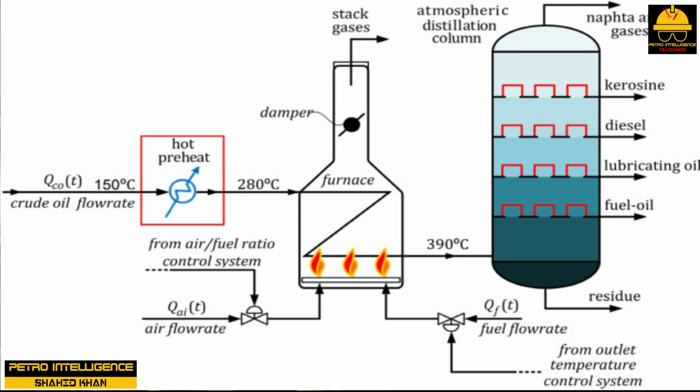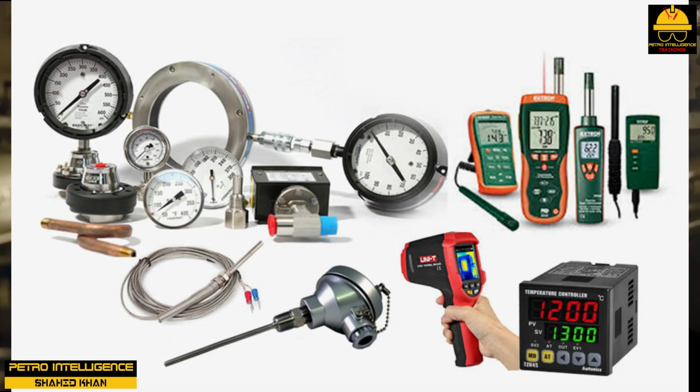Fahrenheit scales operate by using 32 degrees Fahrenheit as the freezing point for water and 212 degrees Fahrenheit as the boiling point of water. Celsius uses 0 degrees Celsius as the freezing point of water and 100 degrees Celsius as the boiling point of water. Process operators use Fahrenheit and Celsius thermometers to measure temperature. Local temperature indicators usually contain a bimetallic strip that differentially expands with increasing temperature, causing a deflection that is correlated with temperature. Bimetallic thermometers can range from -300 degrees to 800 degrees Fahrenheit.